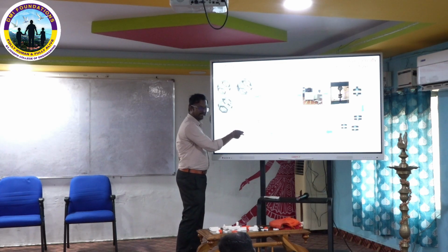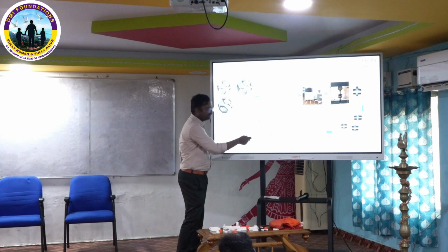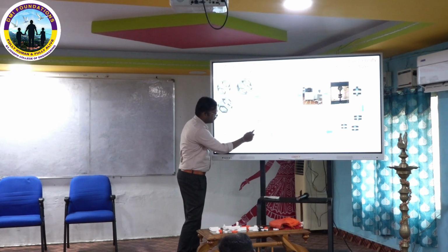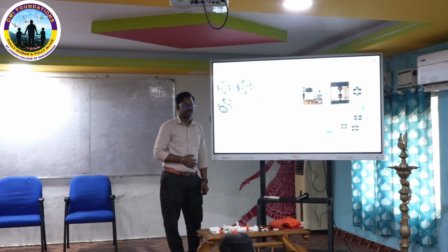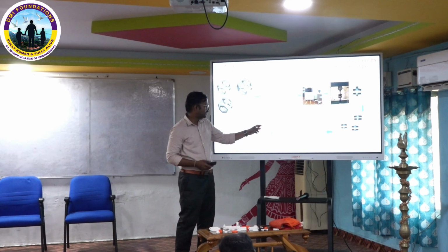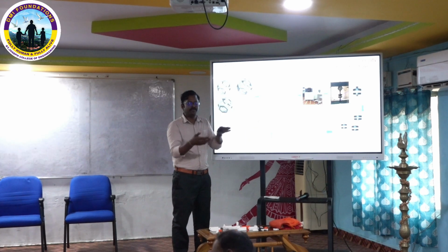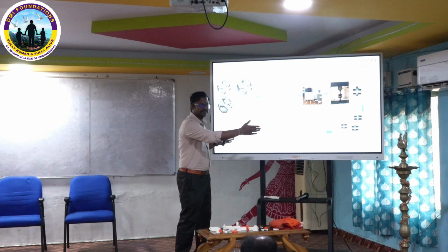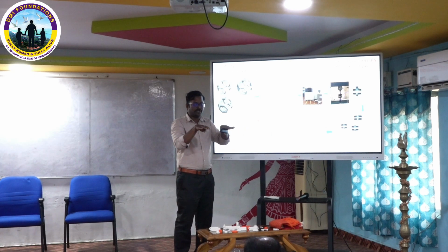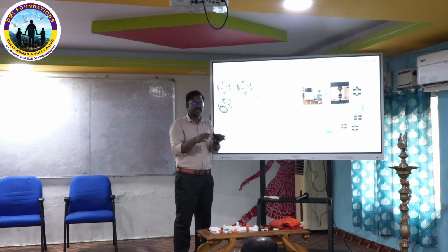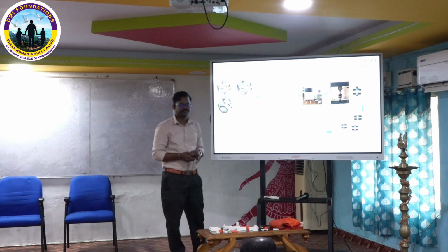This is a single sintering line, whose cross section is a circle. Hatching distance is the distance between the mid line of one and the mid line of the next. If you reduce the hatching distance, both layers get more overlap, so over-sintering will happen and it will easily break. If you make the distance more, the overlap is minimal, so holes and pores will be there. It will affect the density and properties also.